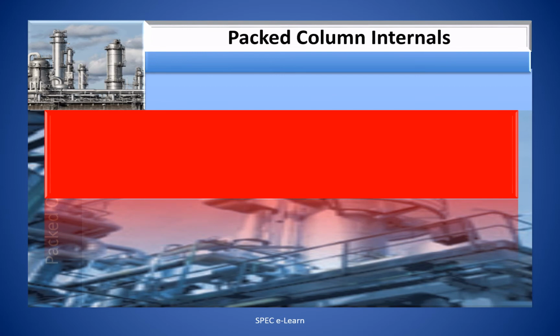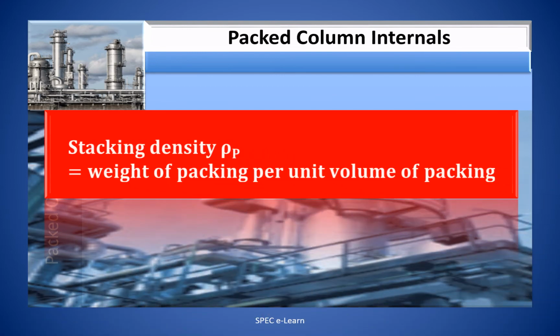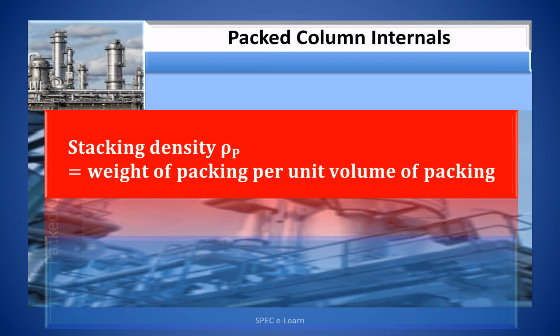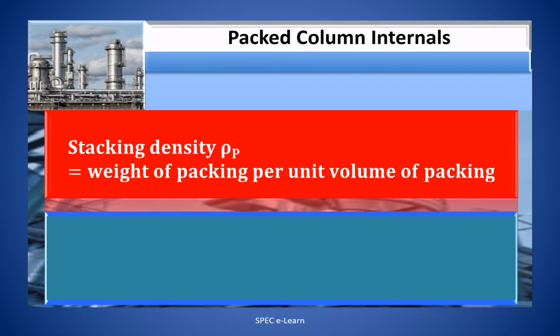Another parameter included in the packing characteristics is stacking density, rho P. It is equal to the weight of packing per unit volume of packing, expressed in units of kg per cubic meter of packing.